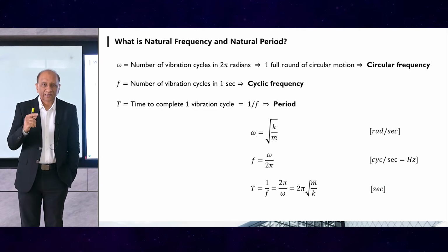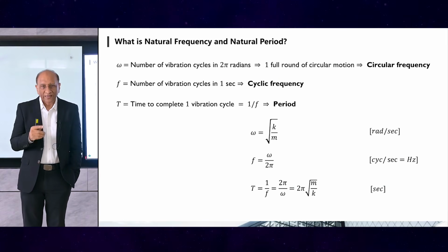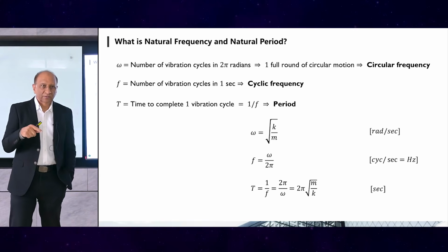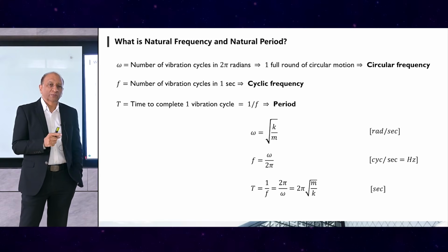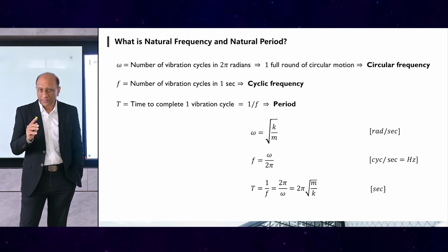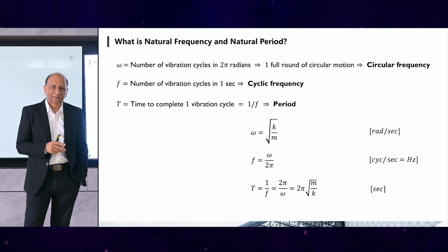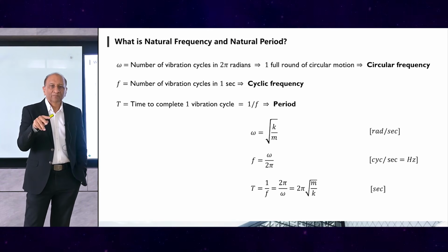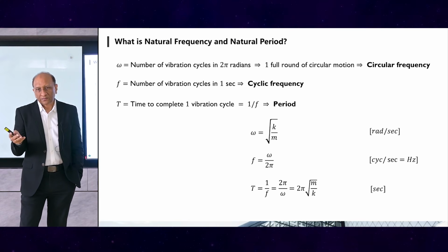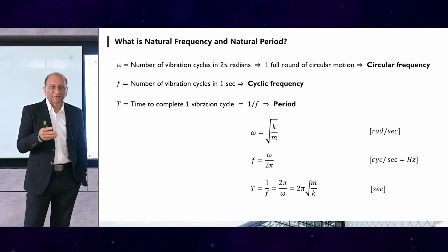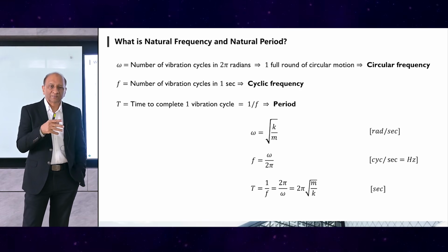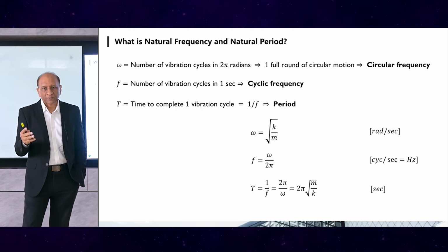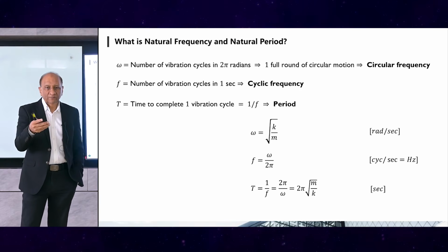The omega, which is the rotational or cyclic frequency, and which is a ratio, square root of the ratio between stiffness and mass, nothing else. So that means if we know these 2 things, this can be computed. And the frequency is derived from there by dividing it by 2 pi, as we saw before, and then the period, or time period, some people call it, is then the inverse of that.